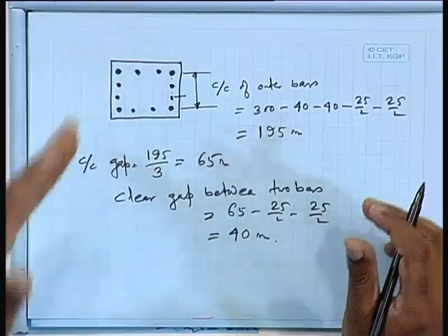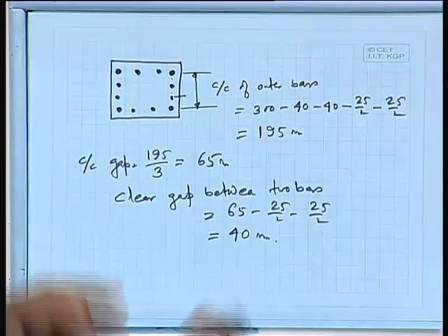It is not desirable, because then the section will be weak and crowded with so many bars. Even if 6 bars are there, the percentage increases. Here we are getting 6 point certain percentage. I am not talking about the code provision. So, 6.29%. It will be 9% then, because 50% of that will also be there.